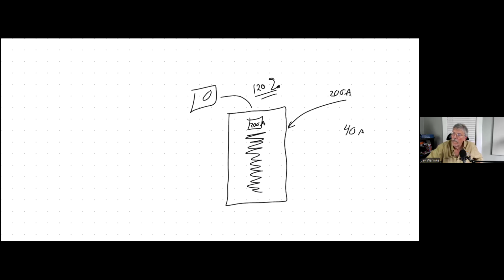So we could come in with an inverter to an AC disconnect, and then connect into a double pole breaker, which you want to locate as far away from the main as possible. What's the maximum size breaker that could be connected in this scenario? It's going to be 40 amps, because that deals with the 120% rule.